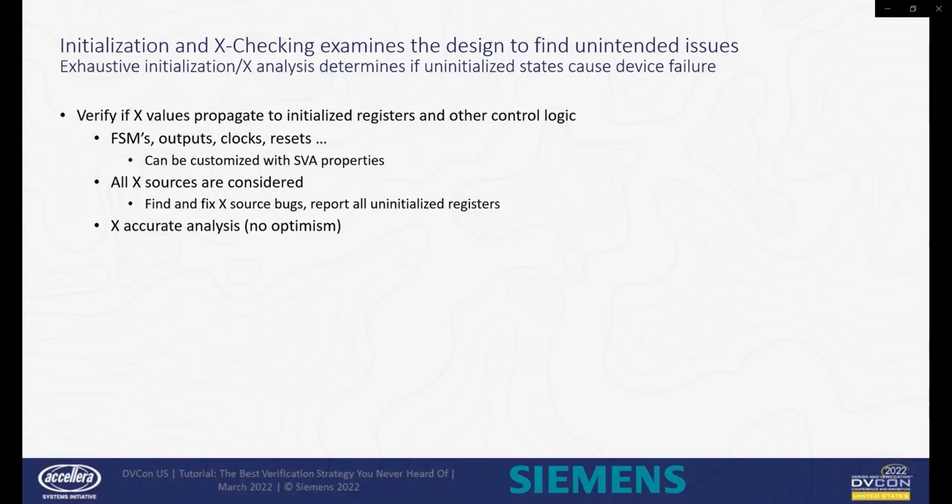Most designs will have some uninitialized registers or other X sources. The goal is to make sure that these X sources don't corrupt registers that were initialized or other control logic such as outputs, FSMs, and clock reset trees, to name a few. The analysis should not have the same limitations of optimism and pessimism seen in simulation.